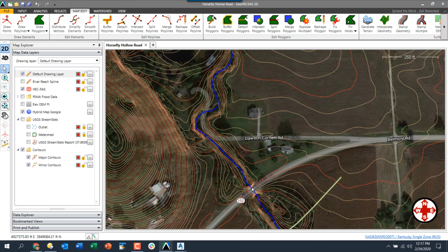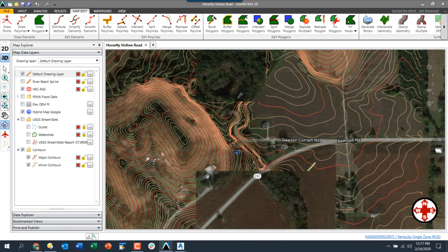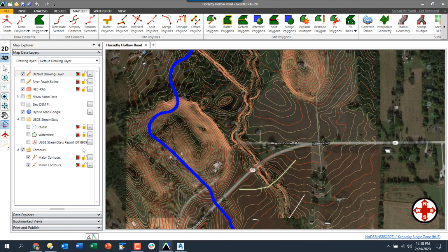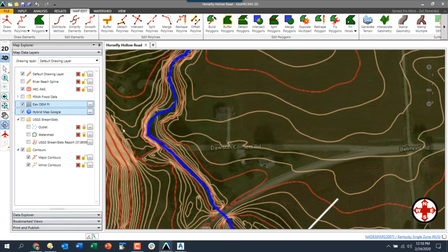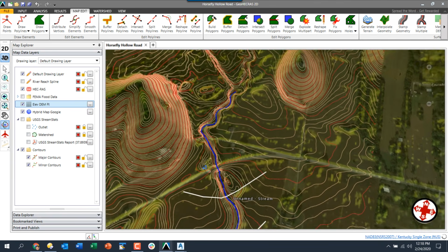We're not worrying about the roadway. We're more worried about where the water's contracting inward. Here it's pretty narrow, right? You see this is almost like a canyon here. If we go look at it in 3D, if we rotate it around into a 3D view, well, I don't have an elevation grid loaded. Let's turn that on. There we go. Now it's got an elevation grid. Otherwise, it's just contouring it in space.